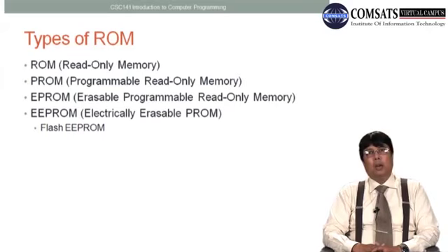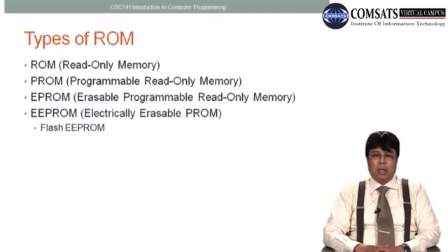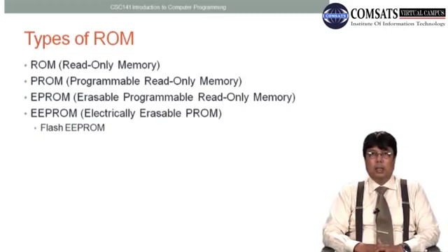The user can modify the contents of the data without taking it out of the socket. While staying within the socket, you can use it, you can program it, you can erase the contents using programs that can generate electric pulses that erase the data, and then you can rewrite it.